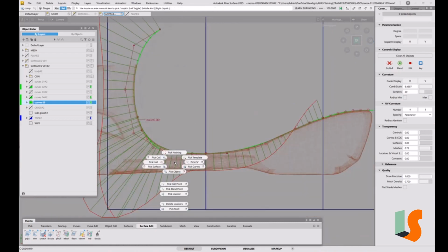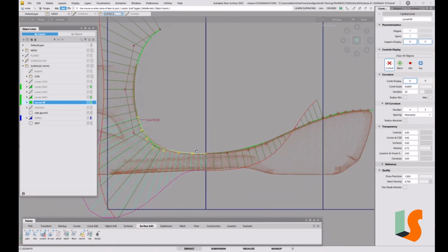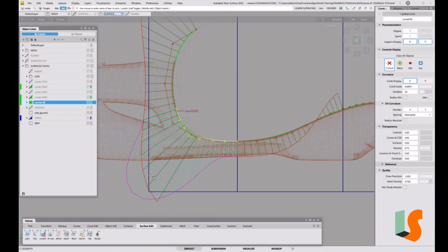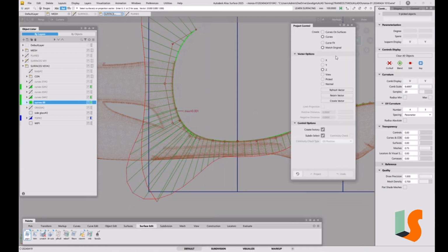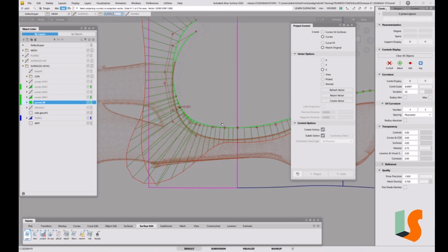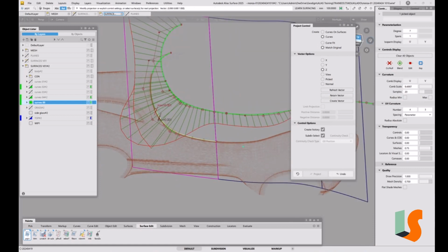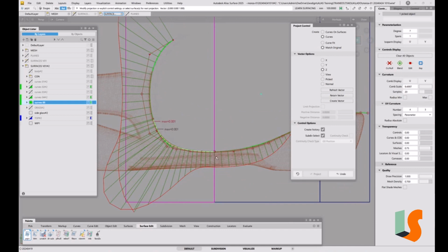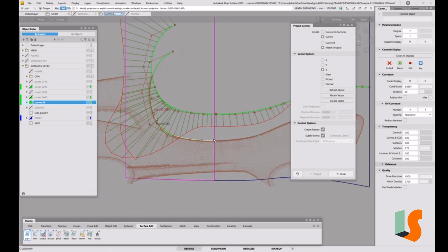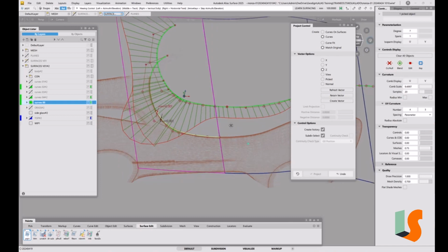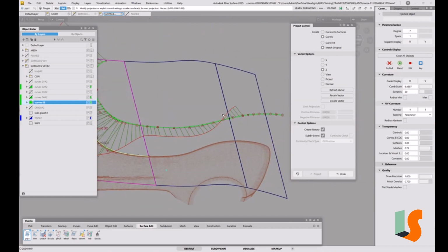So we've got a curve in here. Actually, I got rid of the one, didn't I? I got rid of that curve that came out here because we didn't really need that. Now this is degree 7, so this should have no problem projecting, I would imagine. So let's try that. So I can take it out of the view slightly so we can see it better. And the result is 0.001, so that's fine. And because we trim these curves back to these edges here, we know that should end exactly on that edge. I mean, it's always worth checking when we come to that point, but pretty certain that point is on that edge. That's what it should be.